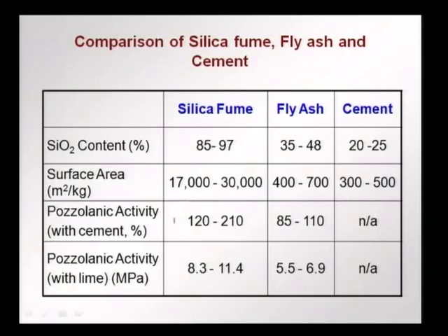The pozzolanic activity also is much higher because of the high silica content and also its fineness. It is much higher than fly ash. In terms of pozzolanic activity, where this material is mixed with lime and we see what is the strength gain, we also see that it is better than fly ash. In pozzolanic activity, we are looking at increase in strength with respect to a cement concrete. So, these are tests which indicate how active or how reactive a mineral admixture is.